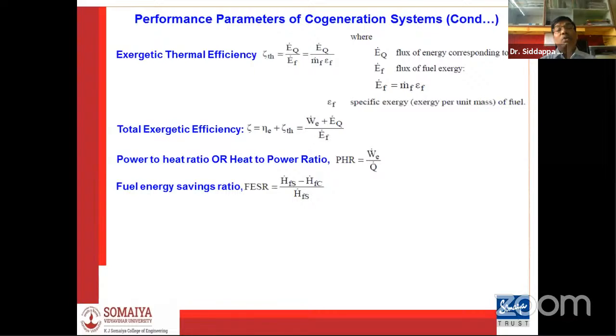And if I take the condensate back and heat the feed water or supplementary water required in the economizer, then the temperature of the water entering the boiler will increase. Instead of a condensate temperature of some 50 or 60 degrees at the saturation pressure of the condenser, it may go to 70 or 80 degrees if you use the economizer.